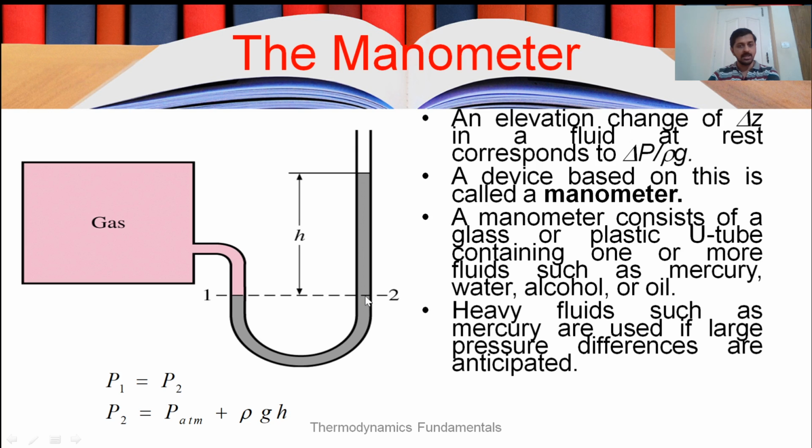So by noting down the pressure at point 2, you will be able to evaluate the pressure at point 1 and thereby the pressure of the gas inside this tank.